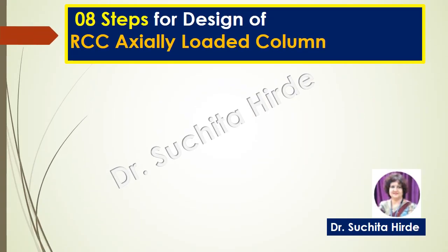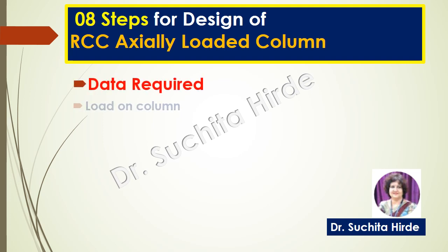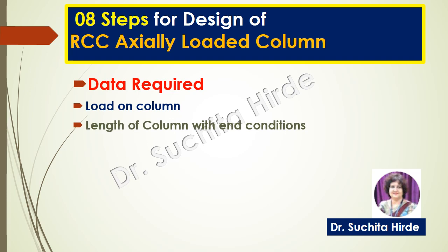Columns can be square, rectangular or circular in shapes. For design of column, we will need load on column, length of column with end conditions, and grade of concrete and steel.